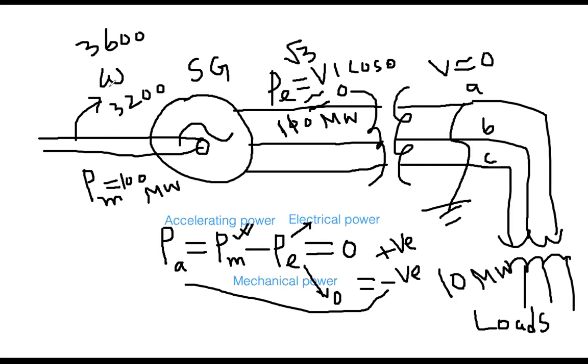And what will be the consequence of that? Can you guess? If the shaft speed increases or decreases, what will be the frequency here? The frequency will be changed, because you know that f is equal to P times Ns over 120, where Ns is the synchronous speed. So everybody see, if your Ns increased, meaning that your frequency will increase.